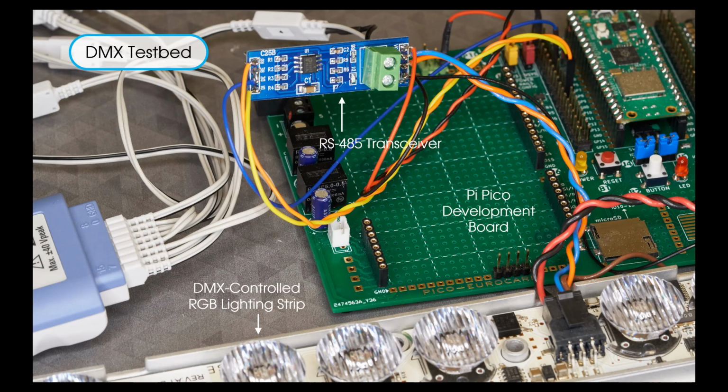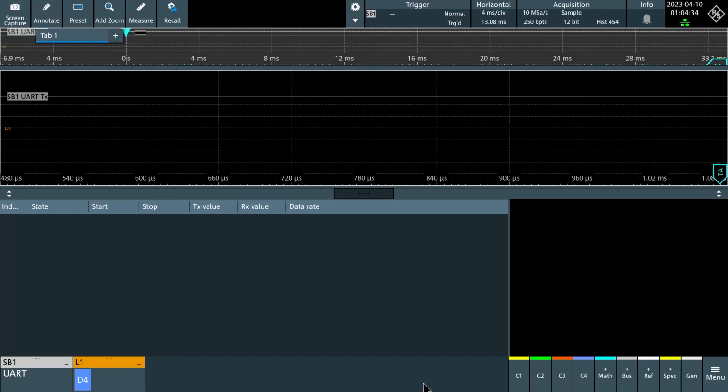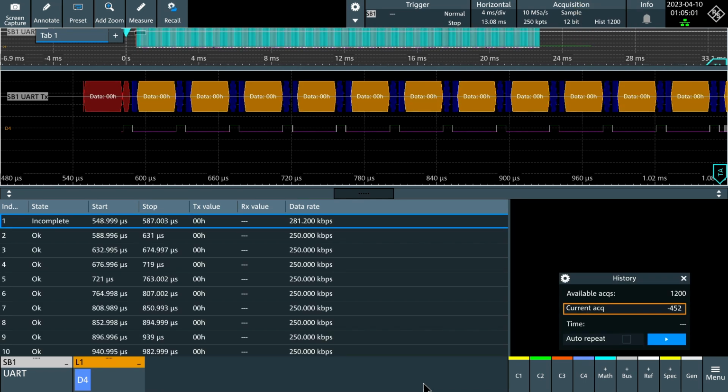They were trigger, history and segmented mode. With the trigger set up to reliably detect the starter packets, the MXO starts capturing and labelling each packet with a history value. There's a fast segmentation setting that allows the captures to occur in segments with no data loss, so that every single DMX packet of 512 bytes was captured and stored. For my test, I was expecting 1200 packets, which is just over 600,000 bytes total, and all of that was captured and labelled in the history correctly.